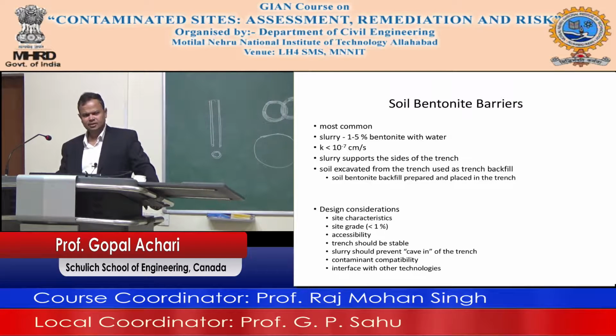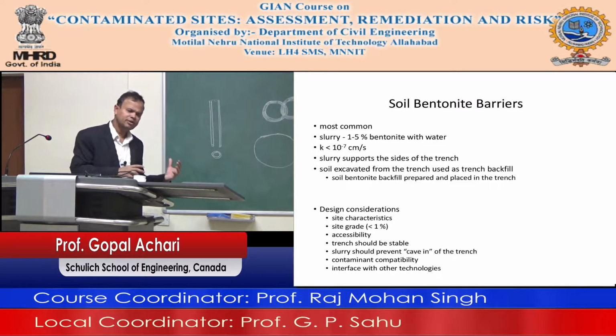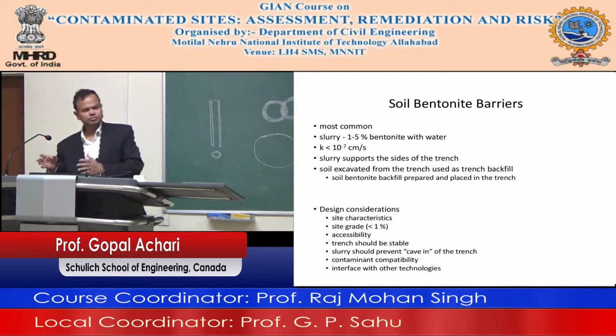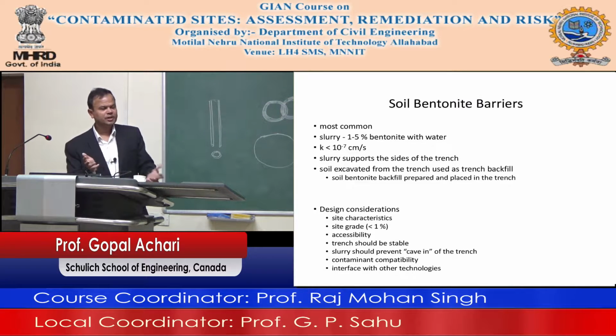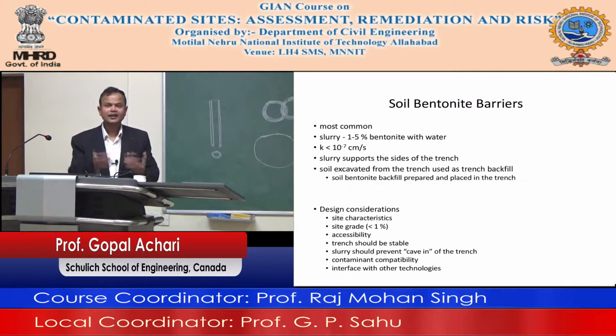Bentonite has sodium cations, and those cations are sitting in between the silica and in between the clay platelets. Once you have a chemical that reacts with the bentonite, with the sodium, and exchanges it out, then you have a situation where the integrity of the bentonitic liner will get compromised, and it is not inert. It is a reactive material. Are you with me on that?